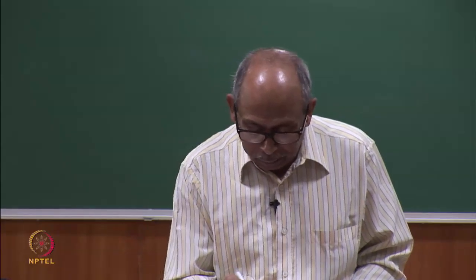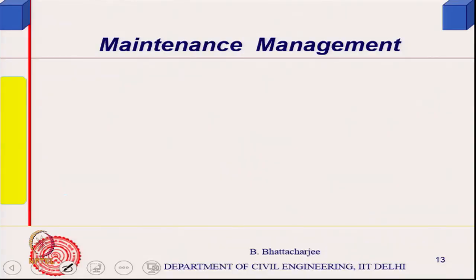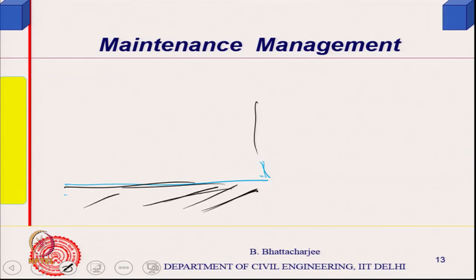Another example I will give you, you might have seen balconies, and then you have a railing there, of course a standing railing should be there. This is a balcony floor, with the railing standing there. Now, you normally should have what is called a spout hole here, so that any rainwater coming in drains out, and this should be mildly sloping.